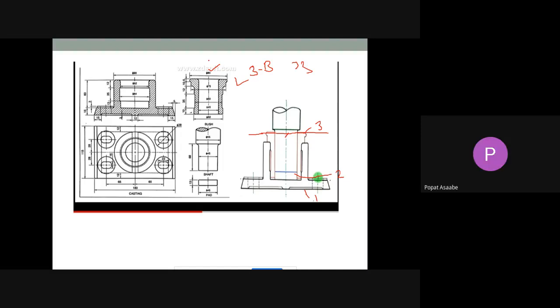Okay. No, it is not 90. It is 80. It is 80, not 90. Okay, it is visible. Can you see it, how much it is? It is 80. This will be the 80 mm diameter. Okay, so from this point we can take here up to 40 distance. Here we can take the 40 distance. Okay, now how much do we have to come down on the side? What is this gap they have given? That is 6 mm. We took 6 mm up to here.